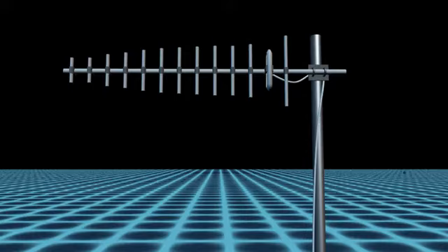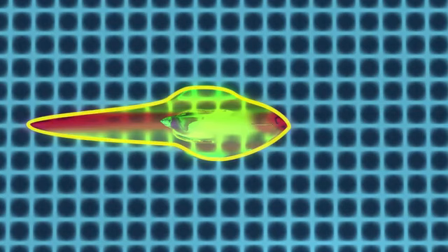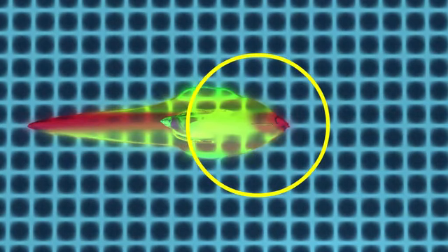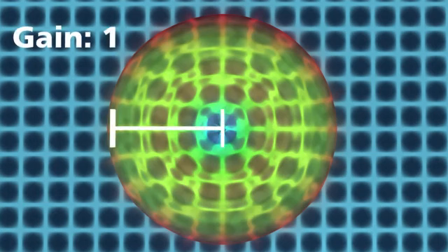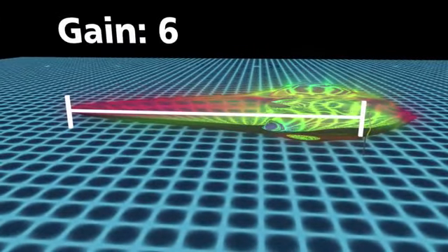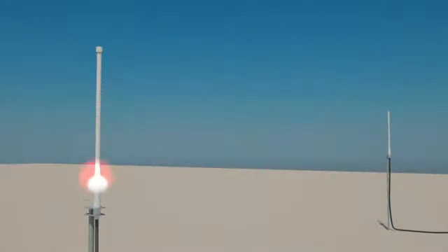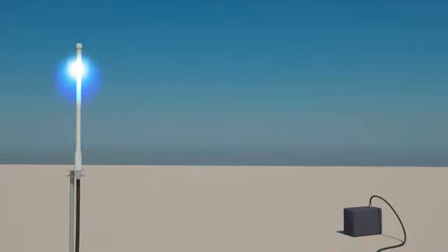Antenna gain is a measure of how strongly an antenna radiates in its direction of maximum radiation intensity, compared to how strong the radiation should be if the same power were distributed equally in all directions. An antenna's gain is used to describe the distance to the furthest point on the pattern from the origin. For an omnidirectional pattern, the gain is 1, or equivalently 0 decibels. The higher the antenna gain, the narrower the beam width, and vice versa. The amount of power that is received by the receiving antenna is proportional to transmitter power and antenna gain. Antenna gain and transmit power can therefore be traded off.